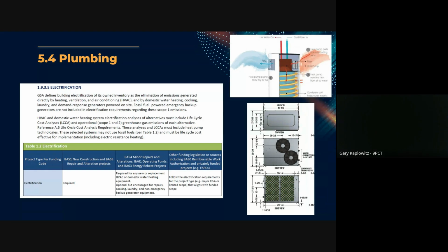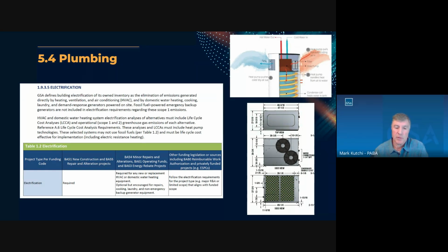Thank you. Yeah, what Lance was referring to, and I just checked it the other day. It's 10 CFR 433, and the entire section now is updated with, I think it's section B, Bravo, with the fossil fuel reduction requirements. So each climate zone and each building type has a limit of amount of fossil fuel that you could use. We did see in one of the recent projects, a courthouse renovation project, they are electrifying the building using heat pumps.